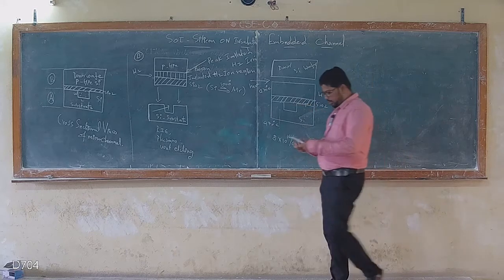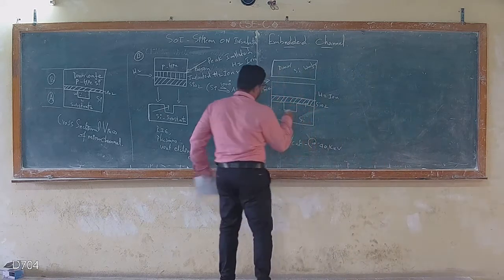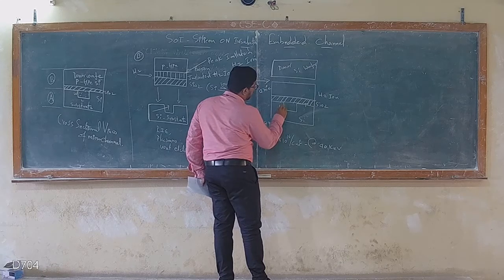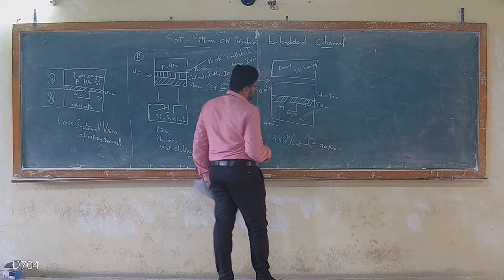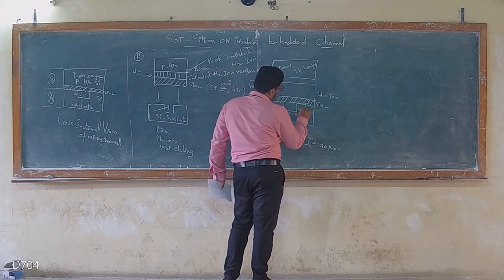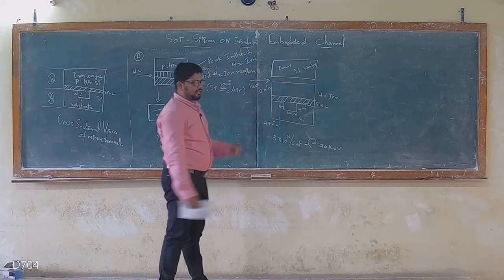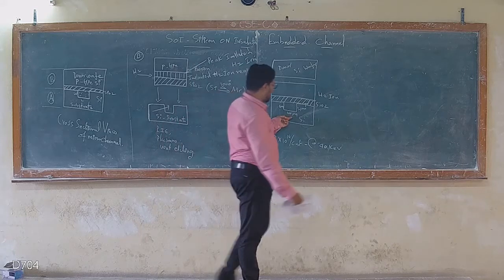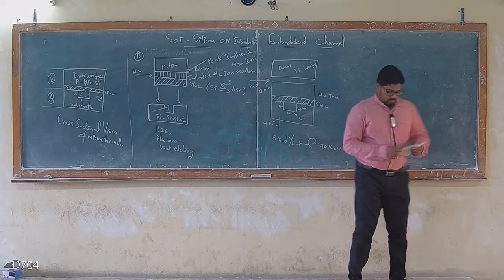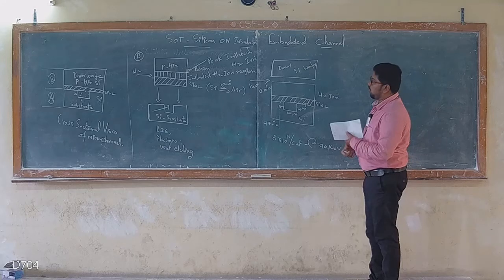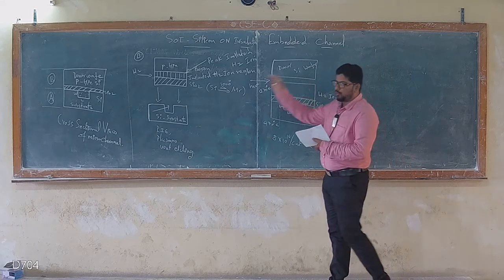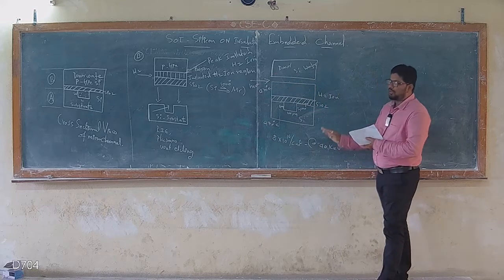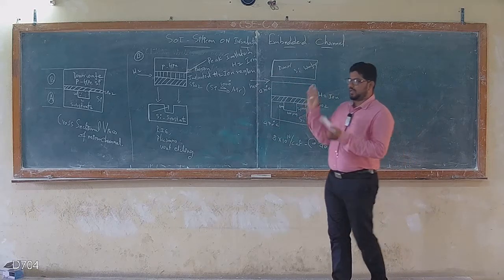The channel width would probably be around 6 micrometers, the length maybe 100 micrometers, and the thickness maybe 2 micrometers. So the length as well as the thickness of the microchannel will be given. This is called SiOI, silicon on insulator embedded channel. This is one of the bonding techniques to bond silicon with silicon dioxide.